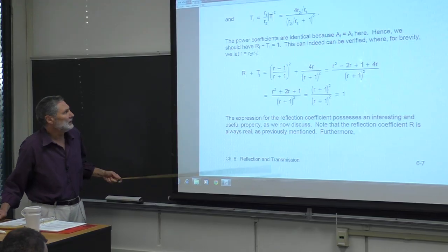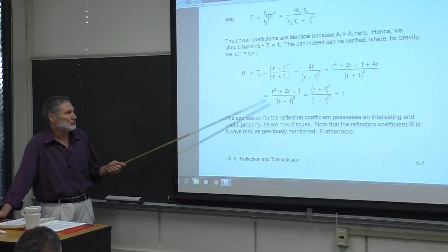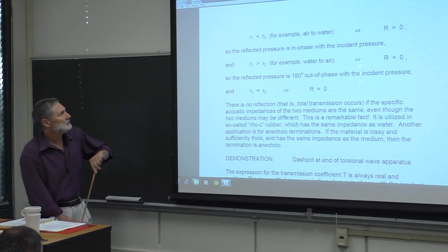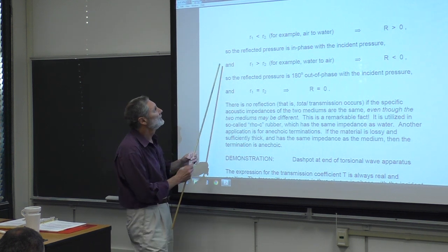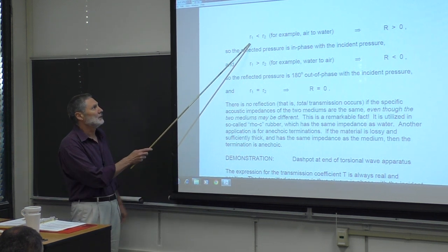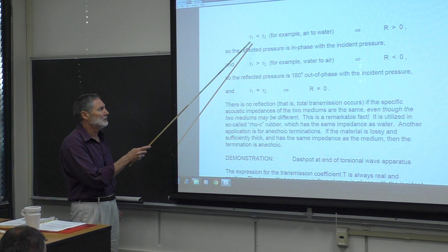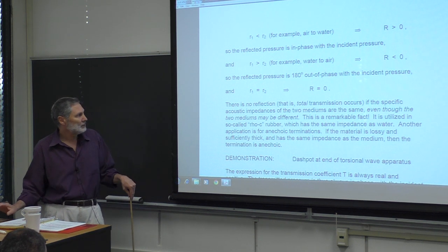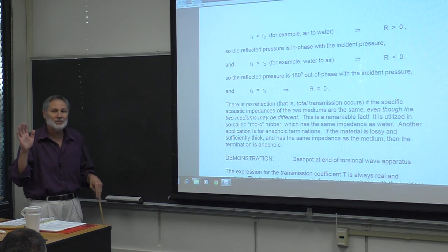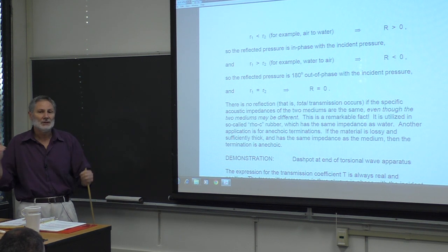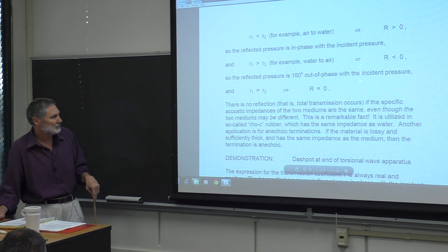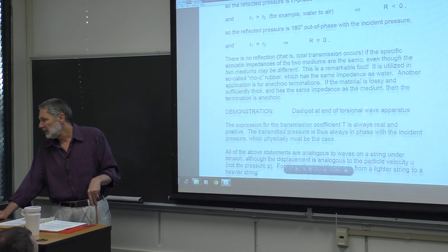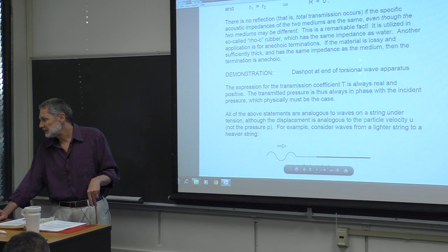We confirmed that energy is conserved here. If it wasn't, we would have made a mistake. And we started to look at some special cases, where the ratio of the impedance is greater than 1 or equal to 1. When the same wave impedance occurs in both mediums, you get no reflection, which is good in some practical situations. We did a demo, and I'm going to skip this.